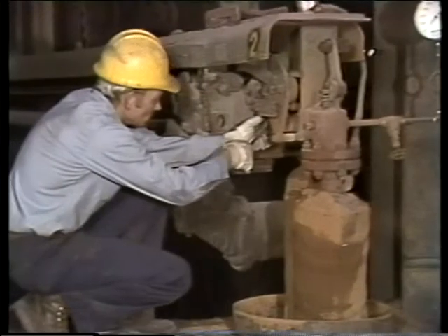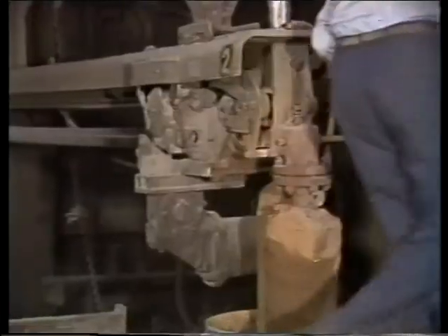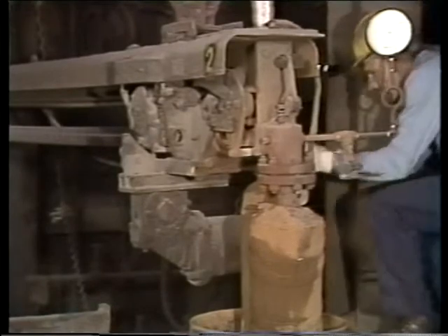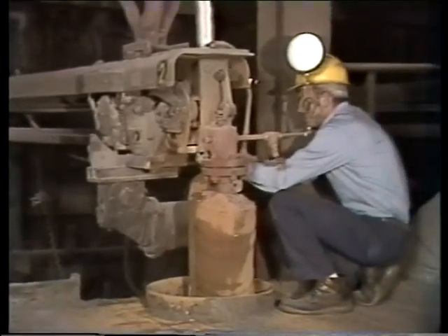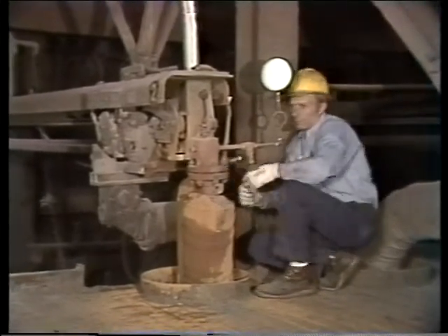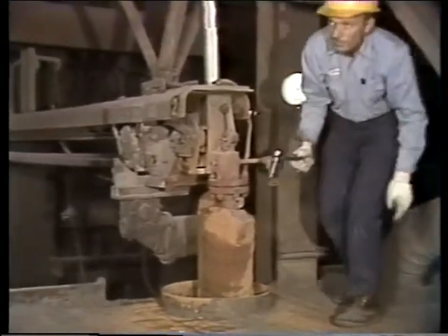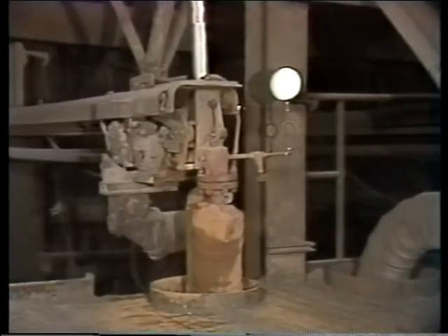Was it just packing that was too tight, or could it be a sagging element or feed tube? That could be the result of blowing pressure that's too low on a long tube retractable like this one. Since the blowing medium not only cools the element but also helps to keep it rigid when it's extended, if the pressure is too low, the element could bind tightly enough to freeze up the soot blower.